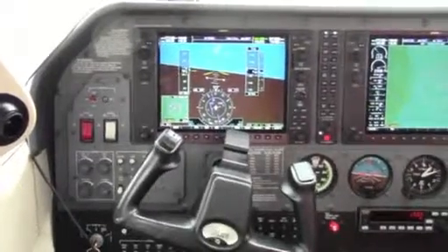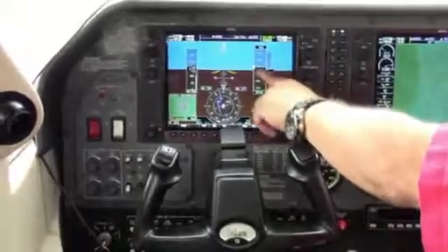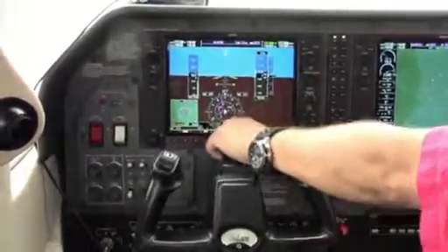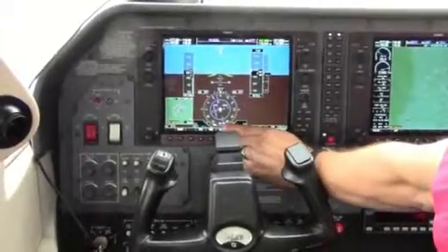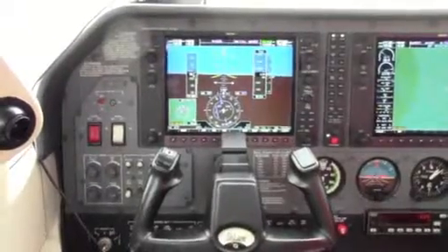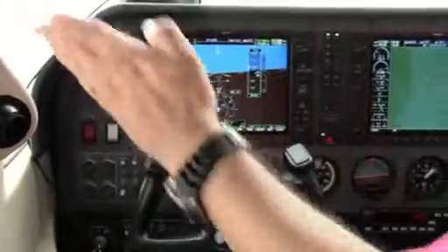Alright, so now I'm going to try to keep 1,000 feet on my altitude, which is the airport elevation in this place. And as you notice here, I'm crabbing into the wind to the left approximately 30 degrees. That's how strong the wind is at this altitude. Remember, as you climb or descend, the wind direction changes and the wind speed also changes, so you need to make the proper corrections. I'm going to try to keep the strut on the center of the runway.